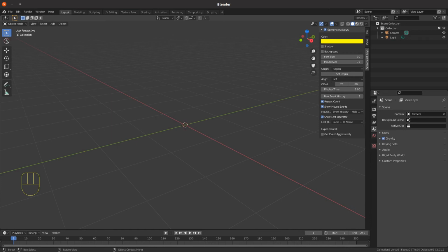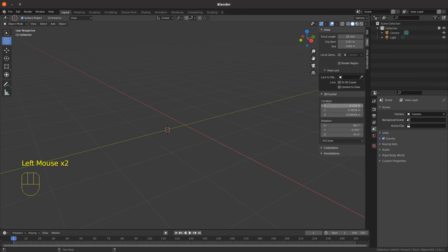Now, the 3D cursor, we've got an option to click and move the position of the cursor. And if we go into view on the transform panel rather than the tools in the view, you can actually add the cursor at specific locations, and you can rotate the cursor as well to match the view that you're looking at, because we've now put the 3D cursor in at an arbitrary viewport view. The rotation of the cursor is different. We can use the various menus that we'll go through in future tutorials.